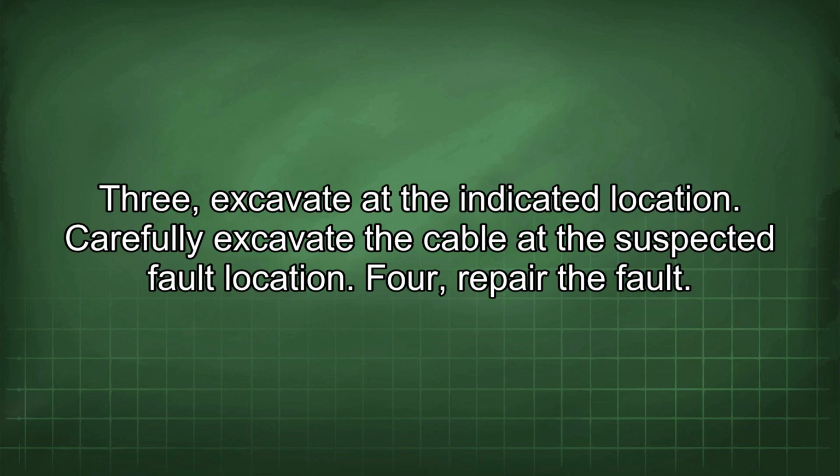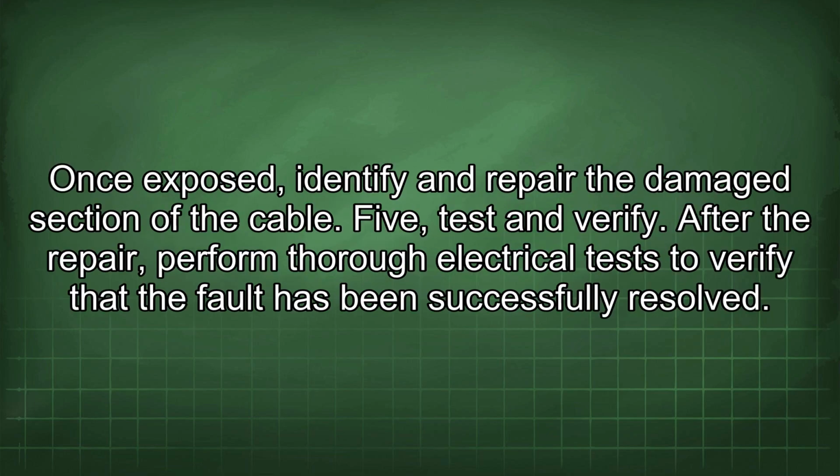Carefully excavate the cable at the suspected fault location. 4. Repair the fault. Once exposed, identify and repair the damaged section of the cable. 5. Test and verify. After the repair, perform thorough electrical tests to verify that the fault has been successfully resolved.